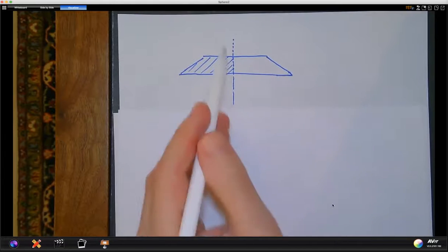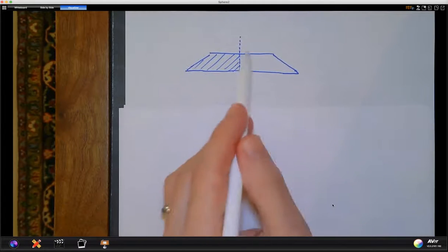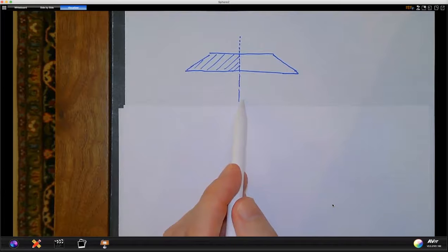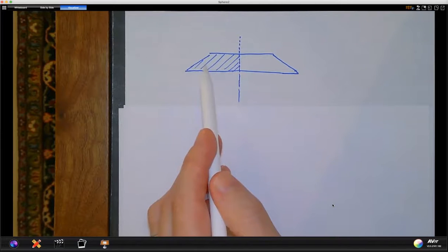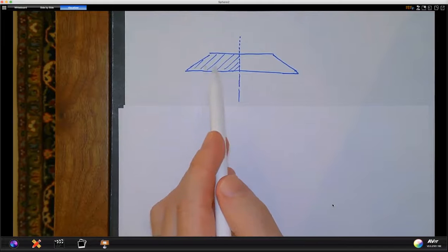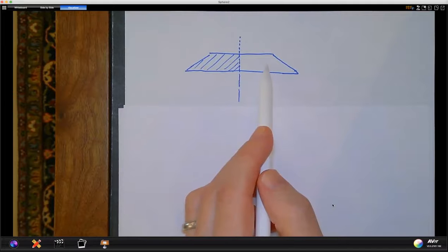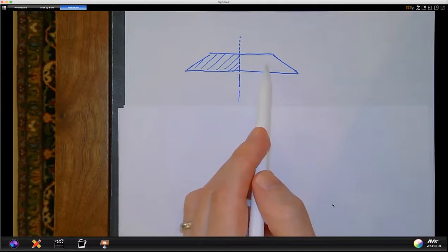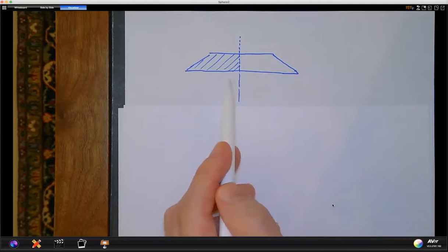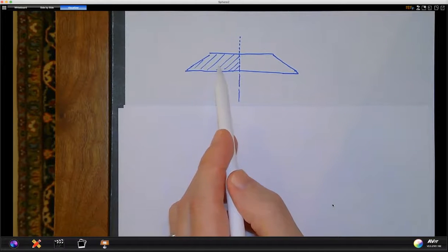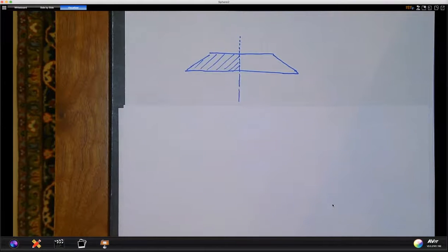And if you happen to be right at the middle, at the center line of the embankment, let's call it, you would enter the chart once to get the left half shaded with diagonal lines, and you would enter the chart once for the right half shown in light color here, just solid white. And as it turns out, you can, as an engineer, save some time and just say, hey, these are going to be the same. They're mirror images of one another. We'll just take the influence factor for 1/2 and multiply that by 2. And does that make sense? Indeed it does.